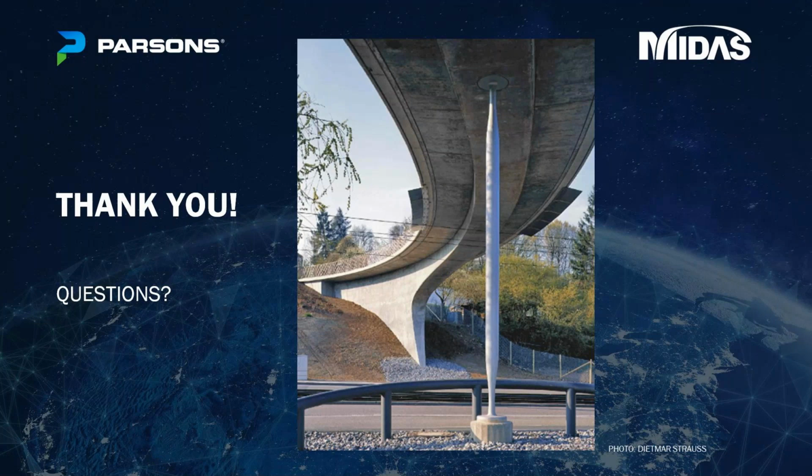So the first question asks, how critical is temperature for an integral bridge? Can it be cable-stayed or a spandrel arch, which you showed us? Yeah, you need to consider the temperature effects. You need to understand what it does to your structure, but the more flexible your structure is, the easier you can avoid these restraining effects, and that will help you to deal with this. So you just need to investigate this, and curved structures can easily move out. When you have a straight structure, you need to cope with this somehow at the abutments. We do this typically with the piles, but I believe when you have curvature in your superstructure, in plan view or vertically, you don't need the piles that need to move.